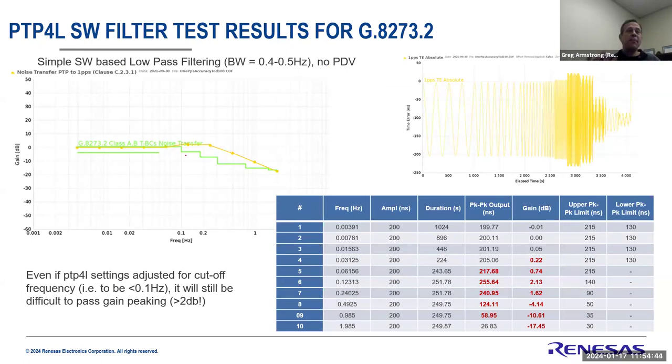And like I said, you can implement a phase lock loop in software or hardware, but there are some disadvantages when you look at software compared to a hardware component. The nice thing about a hardware component is that the traceability and the way it behaves to noise is a mathematical certainty. There's nothing that can throw it off, right? As you feed the noise in, that phase detection is passed to the loop filter immediately. There are no delays. If you correct the clock and feed it back, you see that response immediately as part of the feedback mechanism. So it's very easy to implement a phase lock loop in hardware and get very precise behavior.